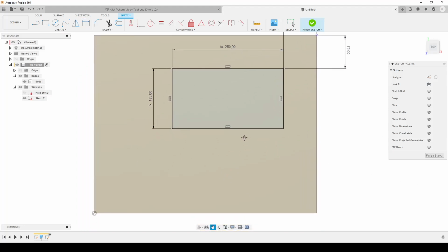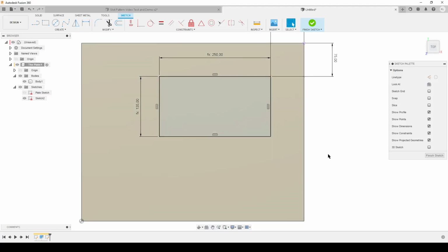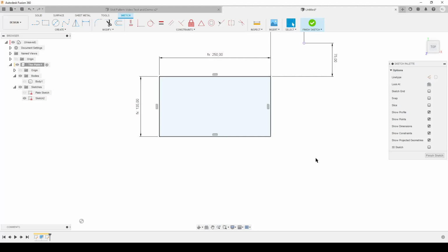So with that, let's see. I'm going to hide the body now because it's going to go flashing around. I'm going to turn on the dimension tool. And the first thing I'm going to do, I'm going to make a line. Make it a construction line from this corner to here. And make another line, not a construction line, normal line. Somewhere here, just up like that. And we're going to make the midpoint between this line and this. So it gets locked down the middle. And we're going to dimension the angle. This was our slot angle.